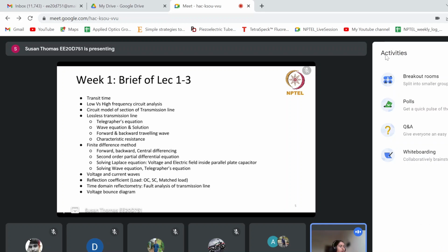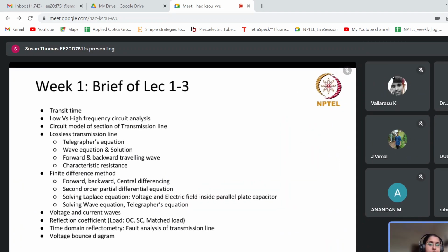Let me carry on towards our discussion on week one, which covers lectures 1 to 3 and the basic concept takeaway ideas from those lectures. The first discussion starts with the notion of delay in interconnects, and discussion on transit time. As you know, if you have already gone through the video lectures, transit time, if you denote it by tau, can be defined as the length of a transmission line divided by the velocity of the signal.